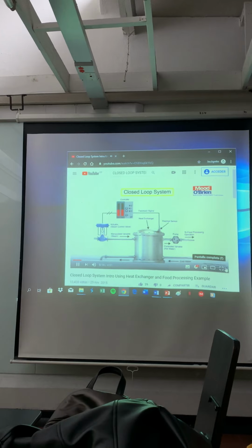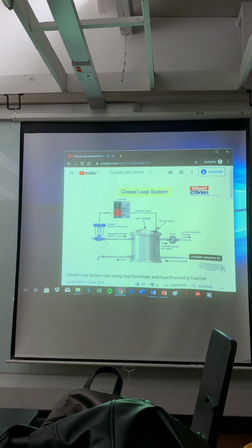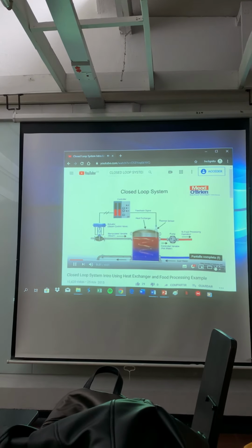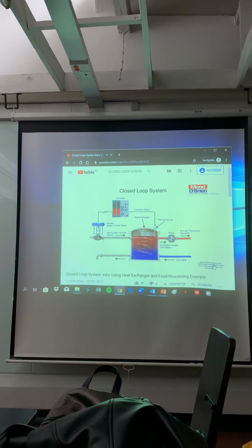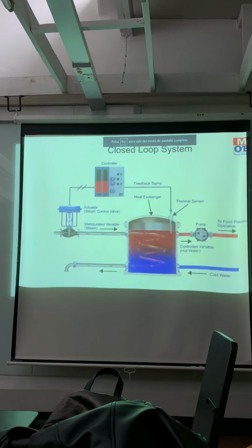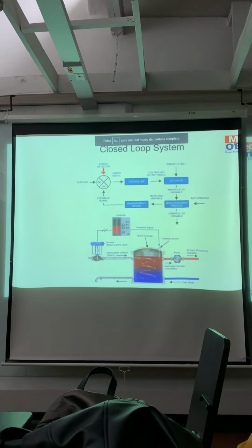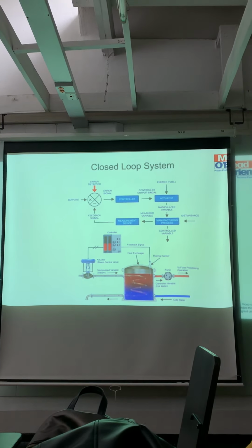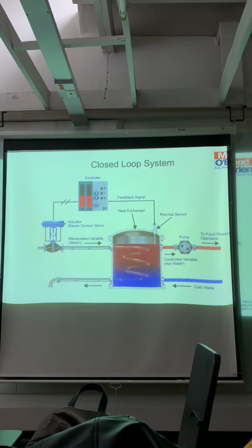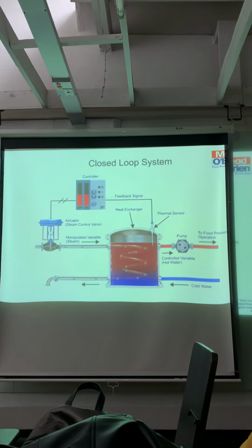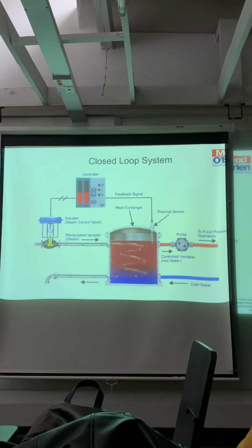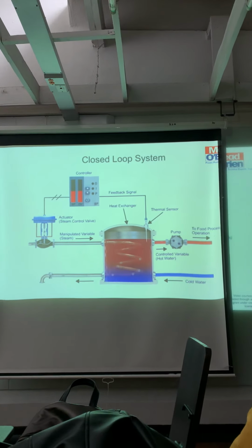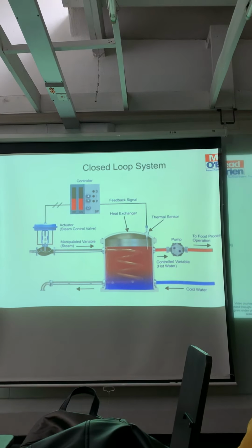The function of a closed-loop system is to monitor and automatically maintain a variable at a desired set point in a manufacturing process. Using an example of a heat exchanger, the operation of a closed-loop system is compared with a block diagram. The heat exchanger supplies heated water to a food processing operation. Cold water enters the bottom of the vessel where the water temperature rises as it passes through steam-heated coils before flowing out of the pump at the top.